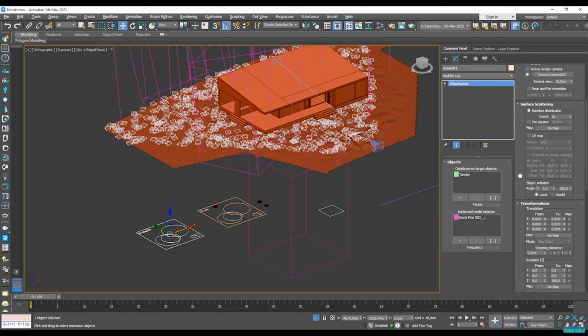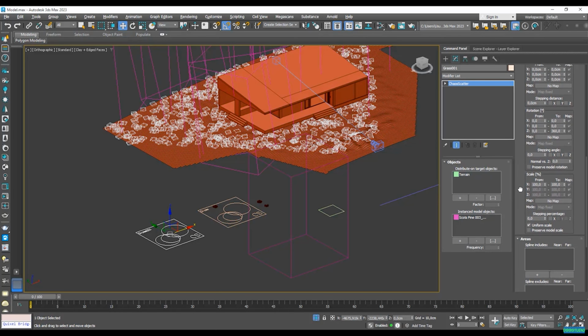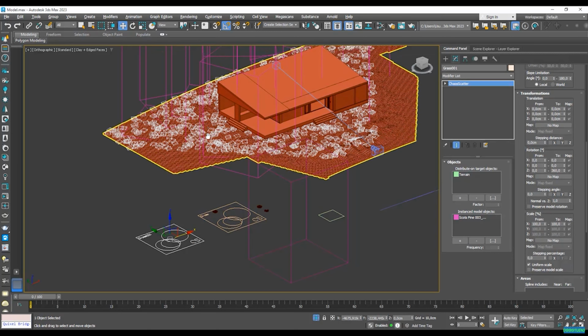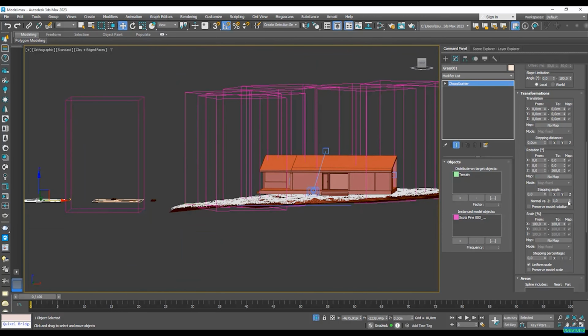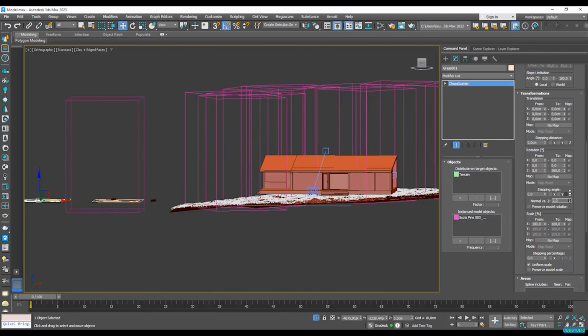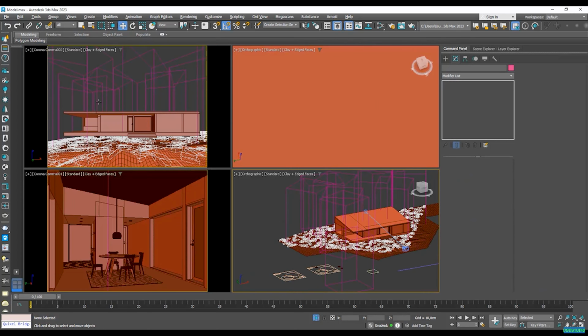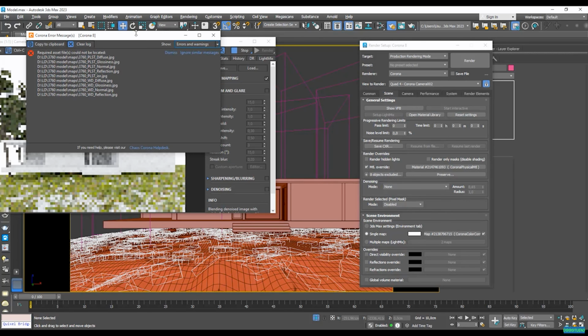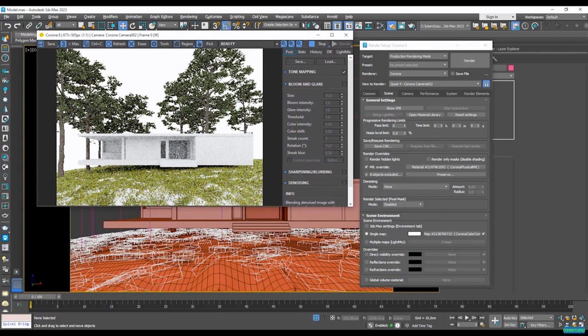And all the way down here where we were just adjusting that parameter, we have the normal versus z. So this actually goes from 0 to 1. Let's just type in 1. And you can see how my trees have straightened up. You can see this tilt, which is very weird for this to be happening in real life. So let's just leave it at 1 right there. Now let's have another look at our interactive render. Okay, so this is looking way better.